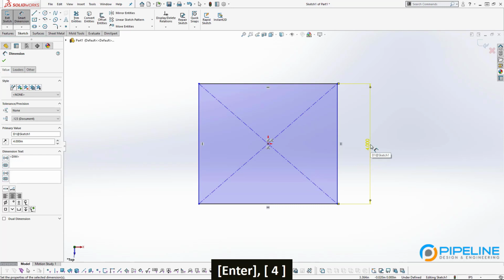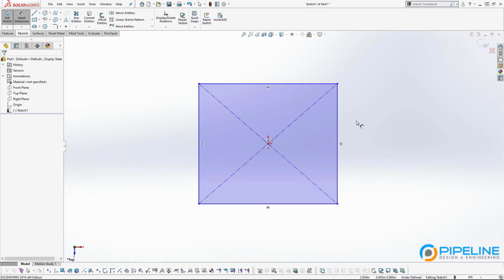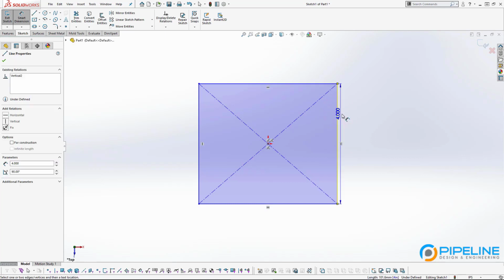Which mouse buttons did you use to click and drag and drop off your dimension? You can see on the bottom of my screen when I do actions, my computer shows the buttons that I'm using in case anything's not clear. When I click here, it's just the mouse 1 button. You just click once on the line you want to dimension, and then it's attached to your cursor after you let go of the mouse button. Then you could put it anywhere you'd like.